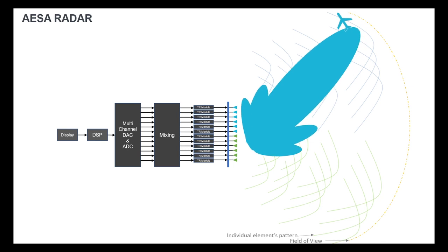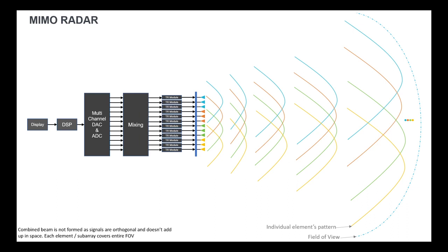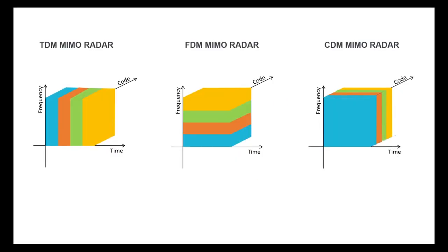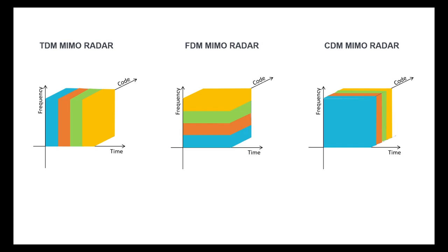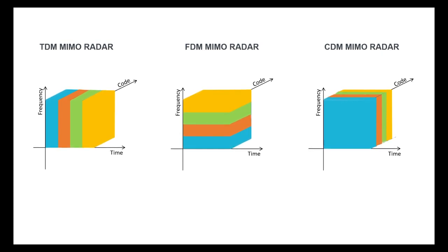However, even when utilizing multiple beams created using subarrays, the AESA radar still takes time to cover the entire field of view. Elements in a MIMO radar system, on the other hand, operate independently and collectively cover the entire 180-degree field of view without the need for directivity adjustments. This significantly improves scan times. The MIMO radar employs time, frequency, or coding techniques in each transmit signal to differentiate them in the receiver element to extract target properties.